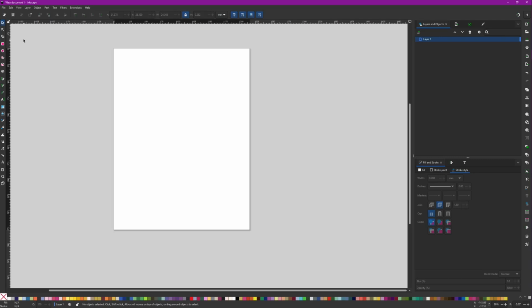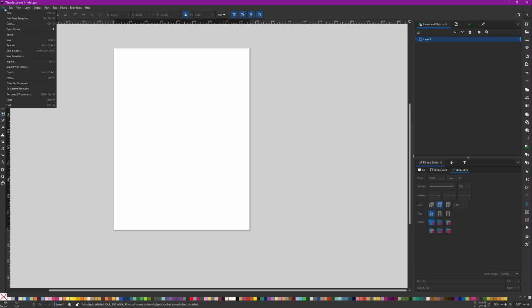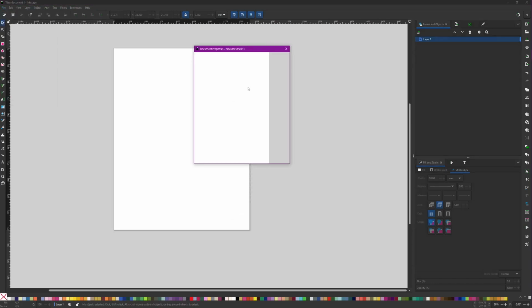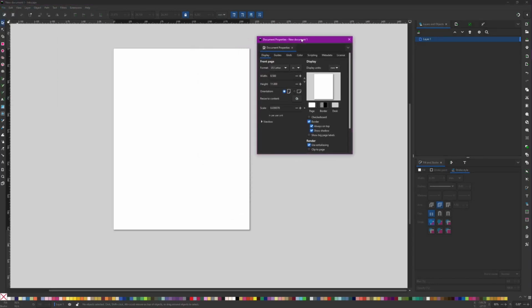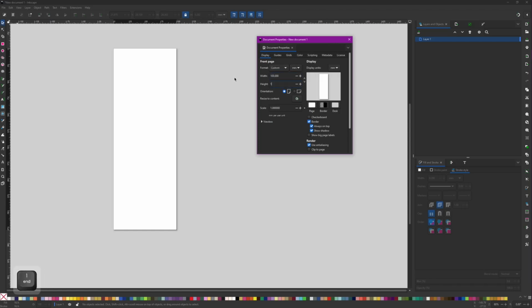So, once you open up Inkscape and you have Inkstitch installed, you want to go to File, Document Properties, and under this first tab here, Display, you'll have your format with preset sizes, your document units, and your width and your height. I'm going to set mine to millimeters because I know how wide my hoop is. And it's 100 millimeters by 100 millimeters.